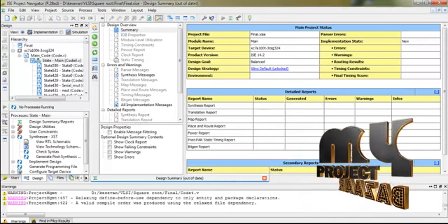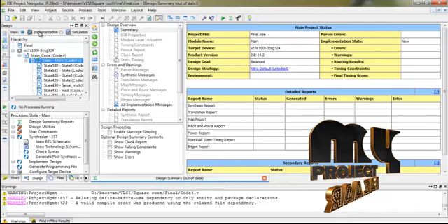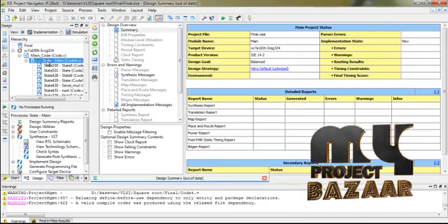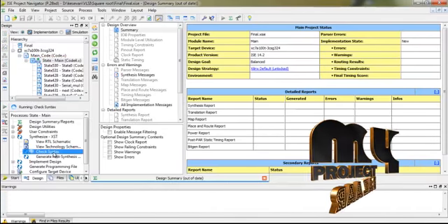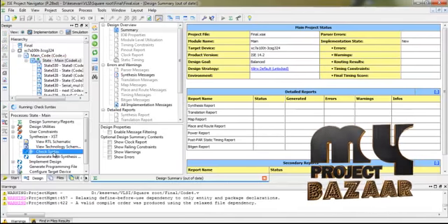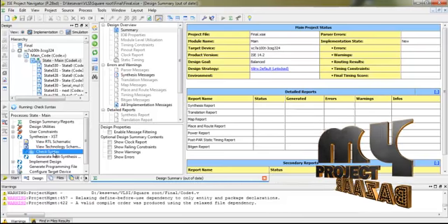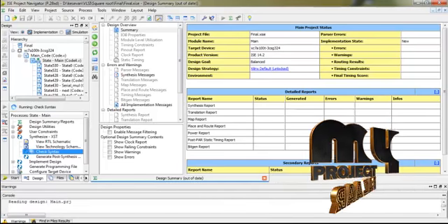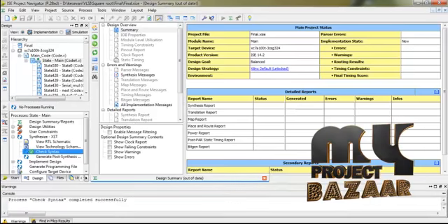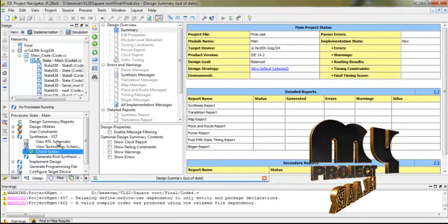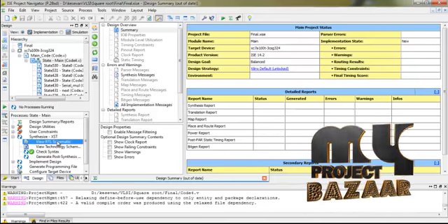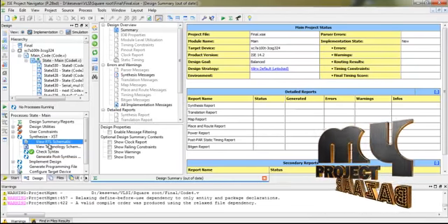Now we are going to the first step. First, select implementation. Then select the main function. Then select check syntax. In this process, we check the syntax errors of our program. Any errors and warnings are displayed in our console log. Now we have no error. Therefore, we are going to the second step. Please select view RTL schematic and run that.